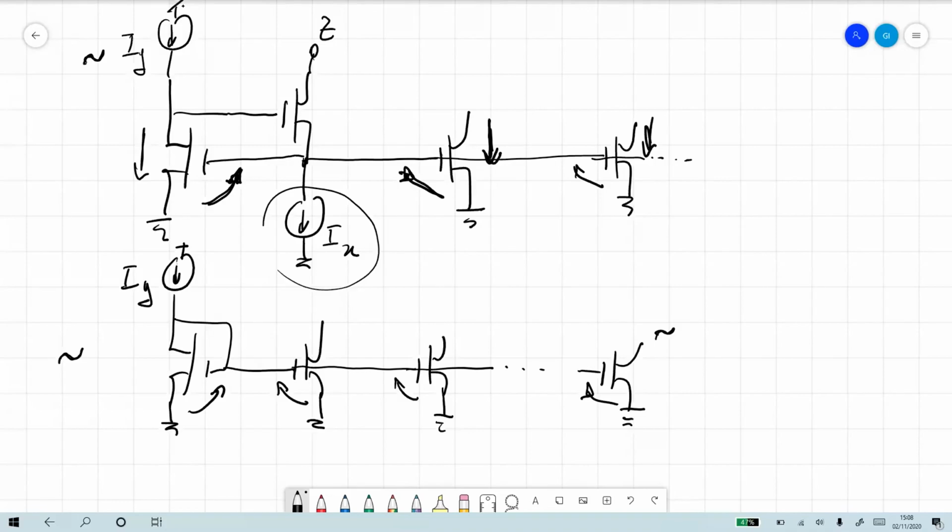So you have to imagine, remember this is sub-threshold, I have some picoamps or nanoamps, maybe I want to implement a filter or something, but these signals are changing over time. And my output signals should change over time in the same way. But I have a very long chain. Maybe I have 1,000 neurons or 1,000,000 neurons, and I want to copy the input to all of them.